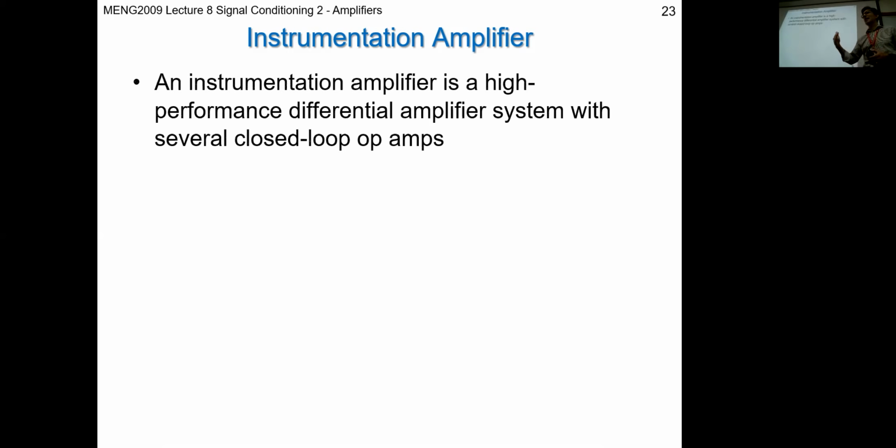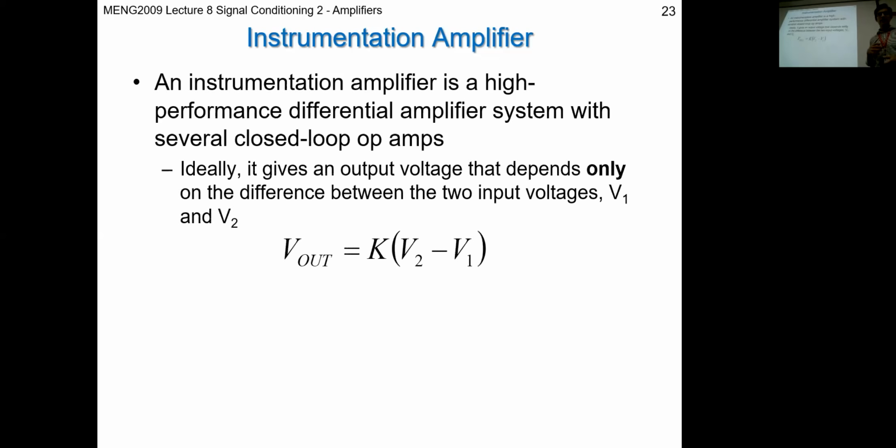And what it does is it stacks up a number of, if you like, subsidiary amplifier circuits into one. And what it should give you is a high quality output, basically. It gives you things like really ensuring you get that high impedance input and the low impedance output. And what an instrumentation amplifier also does is it allows you to change your overall gain by just changing one resistor. Why is that important?